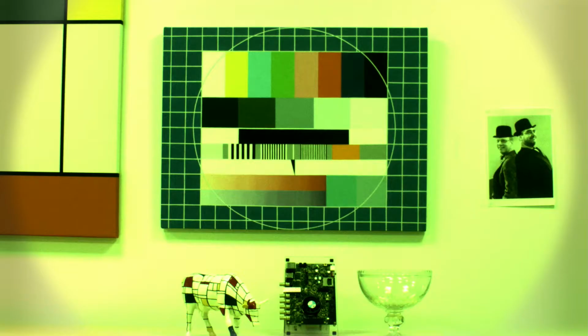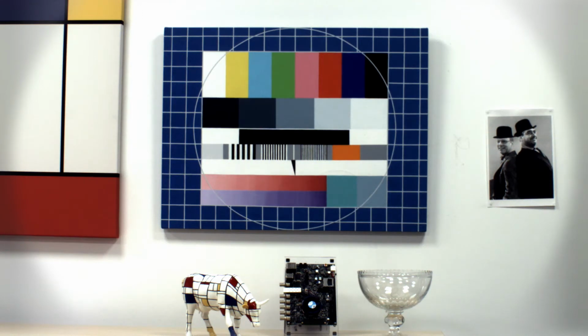Okay, the next block is the black level compensation, which I'll demonstrate with the automatic gain control. So you can see the raw output from the camera here, which obviously the colors are darker and not correctly balanced. And if I apply the automatic correction here, you can now see the correctly set up image. But this image still has the wrong RGB gain levels, and if I apply the automatic RGB gain correction, you can now see a clean image output.